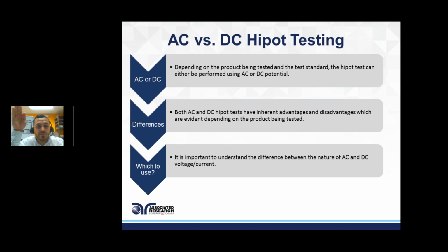It's all purely resistive leakage, and you don't have to worry about failing your test. Luckily, we have some features that I'll discuss later in the DC test that help you avoid failing during that ramp time. It's important to understand the difference between the nature of AC and DC voltage and current, and we'll get into that a little later when we talk about those special features we have built into our DC tests.